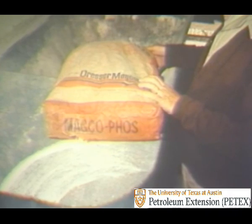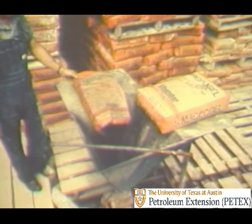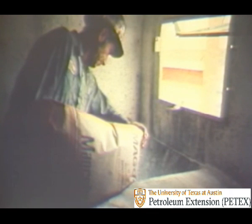So, a different chemical may be used, like the lignite product the derrick man is feeding into the hopper on this rig. Lignite, lignosulfonate, and quebracho are good thinners for relatively high temperatures. But whatever chemical is used as a thinner, the old standby bentonite or gel is added to give filtration control.